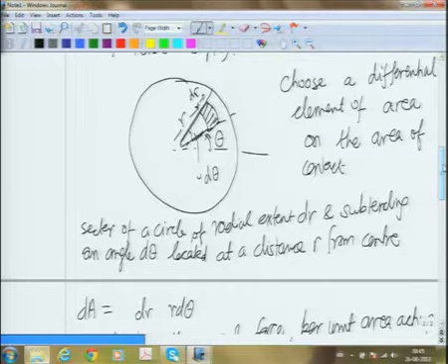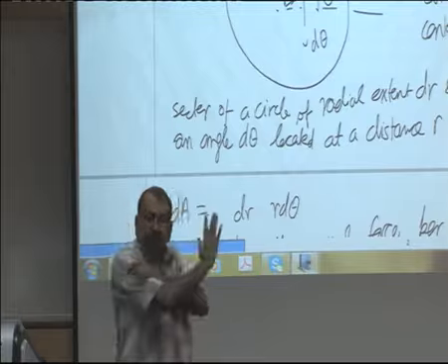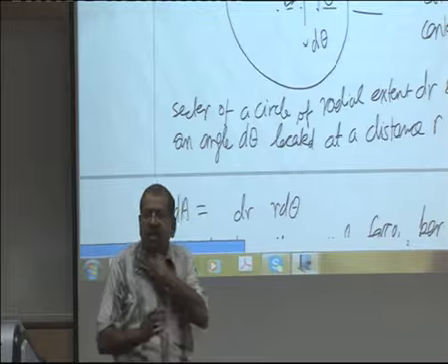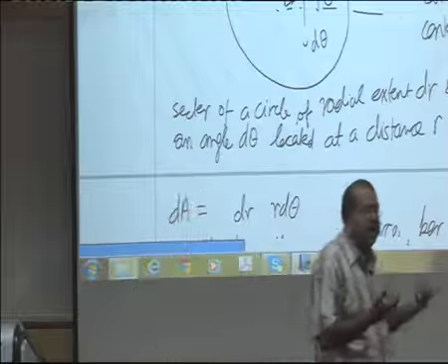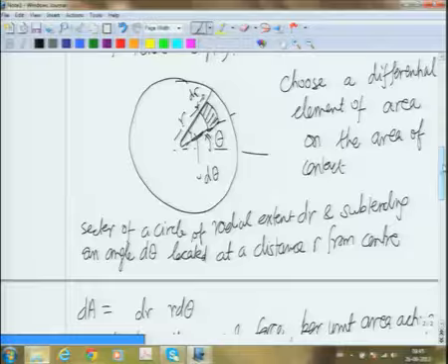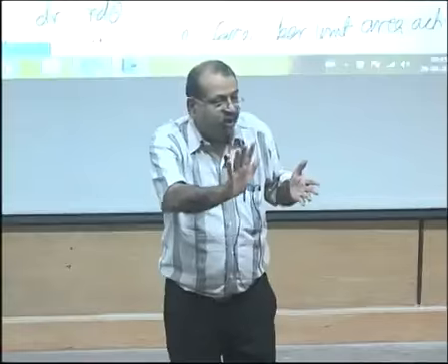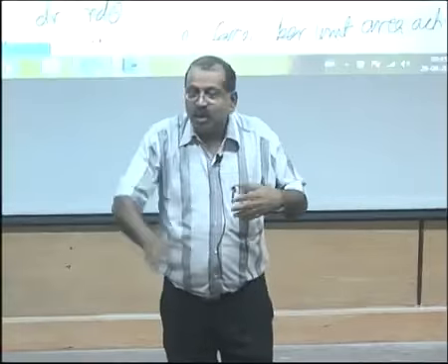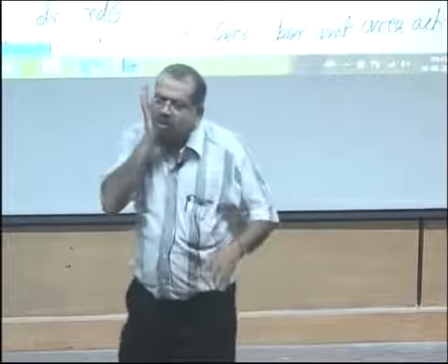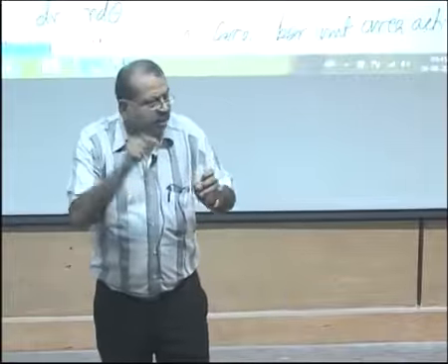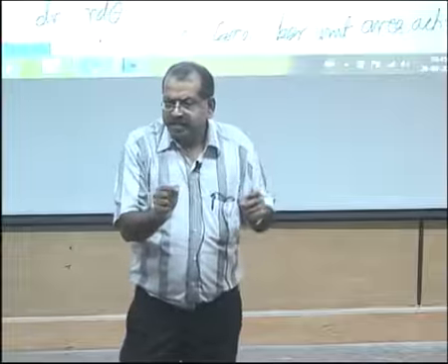On this element, the normal force will be perpendicular to the contact. I denote that as small p. The symbol p has been used because it in some sense denotes pressure. It is a normal force per unit area. Normally we use pressure in a fluid sense, but that's why I use the symbol small p, because it represents the pressure on that element.